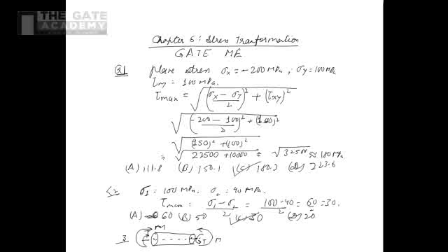So this is the condition which is given. And what is the material property which has to be used, such that the design of this shaft is done using the relationship 16 upon pi d cube times the square root of M square plus T square. Obviously this is the case when we use the maximum shear stress, because this portion is the principal stress and this is the shear stress portion. So this relation, only in tau max we get